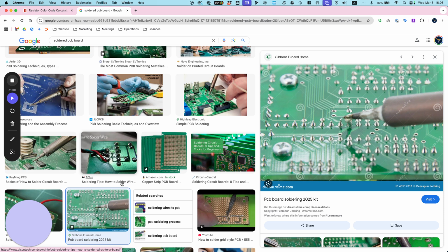I know, but they still have voltage in there. That's right. Even though they're dead in terms of our usage through this onboard chip, they still have voltage in them. Just like any battery, when it's dead, it just doesn't have enough voltage, right? You see right here, we're at 12.8 volts. That's dead. The drone can no longer fly with this, but there's still voltage. So be careful because lithium-ion batteries are kind of dangerous.